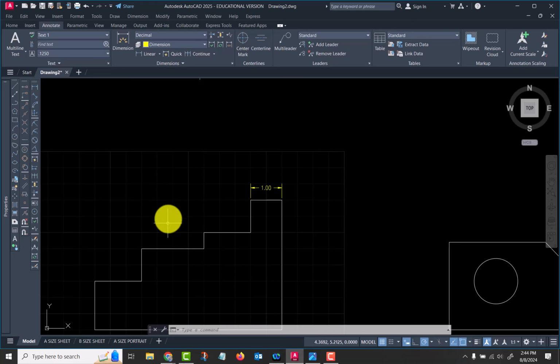But dimensioning to the center of a circle, the location for it, I do a linear dimension from the corner. And if you're doing the 3/8 thing, that's going to kind of throw you off. So we'll start again. I pick where the center line crosses the actual circle. And I come there, and then I come up 0.38, and that places it.